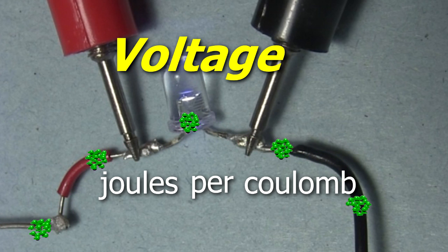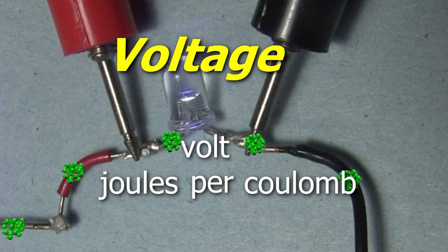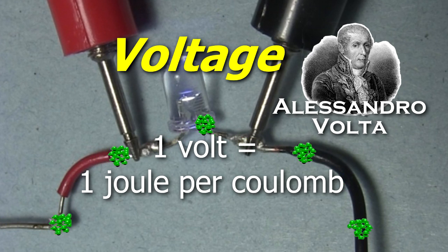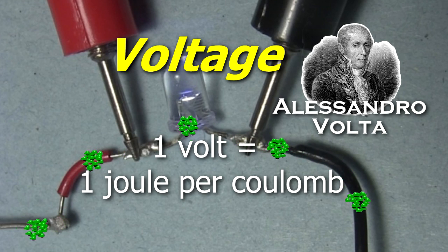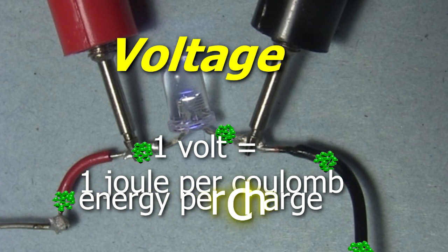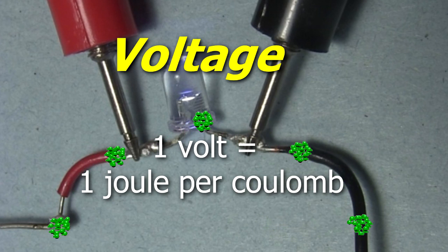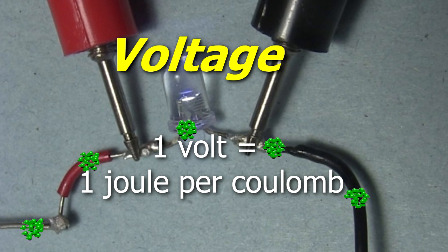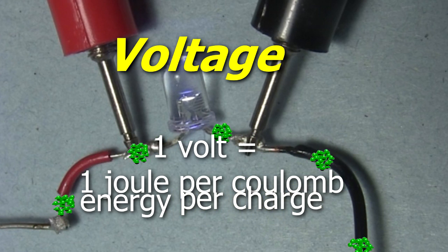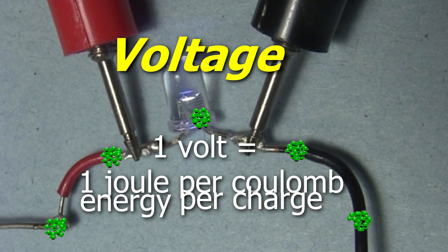You've probably heard of a different unit for voltage called the volt. Saying 1 volt is the same as saying 1 joule per coulomb, except that the word volt is just taken from a famous scientist's name, whereas joules per coulomb tells you that we're dealing with energy per charge. It's much more descriptive. So voltage is an amount of energy. But the important thing is that it's the amount of energy per unit of charge. That's a very important point, so let me illustrate it.